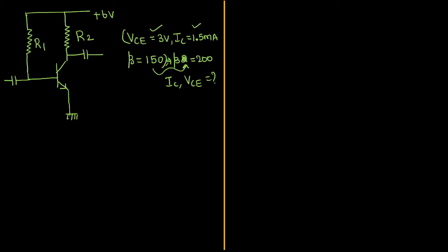You might have got some idea, basic ideas. So okay, done. So what I am doing is, let me try to figure out the answer. First of all, one thing you must understand: in any circuit, if the value of beta is given and they are giving the value of R1 and R2, and the supply voltage VCC is already given, then we can easily identify the value of collector to emitter voltage and the collector current. Yes or no?